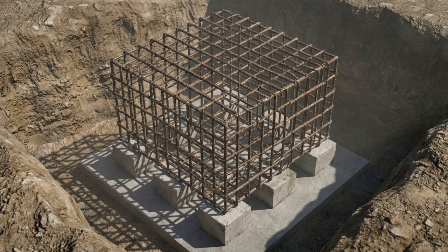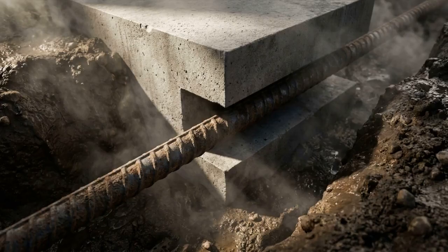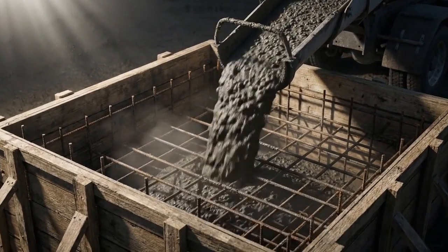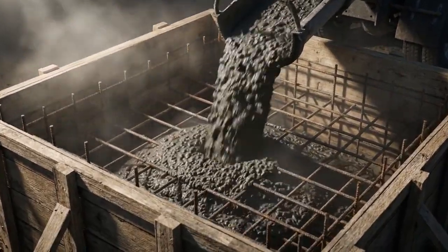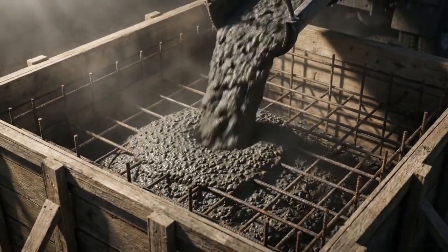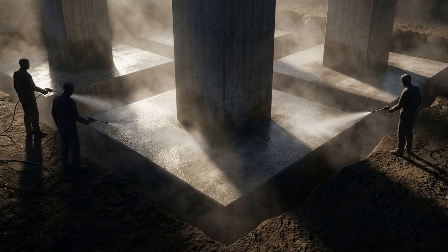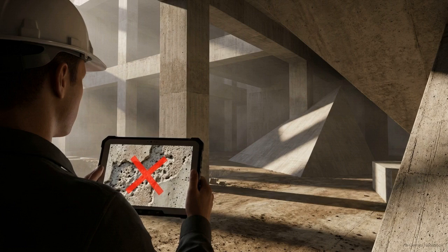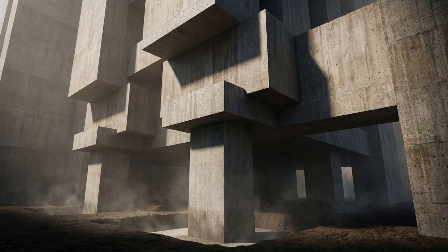Then comes the steel reinforcement cage. These heavy rebar grids must be elevated on concrete cover blocks, preventing the steel from touching the edges and rusting from soil moisture. During the pour, workers use needle vibrators to consolidate the mix, forcing out air bubbles that would leave hollow cavities in the finished concrete. Finally, precise water management during the curing phase dictates the ultimate chemical strength of the concrete, securing it before the soil is backfilled around it. Skipping a single quality control check in this sequence creates structural flaws that diminish the load-carrying capacity of the concrete, leaving the building vulnerable to the very forces the engineer worked to counteract.